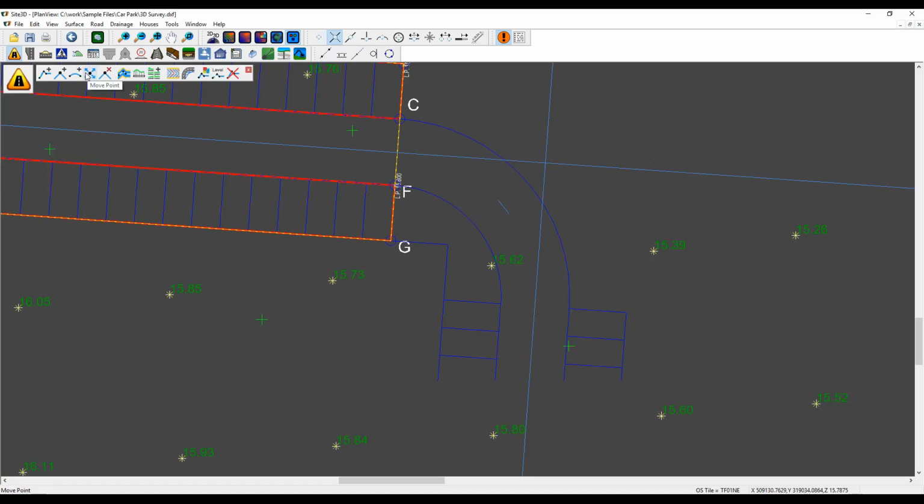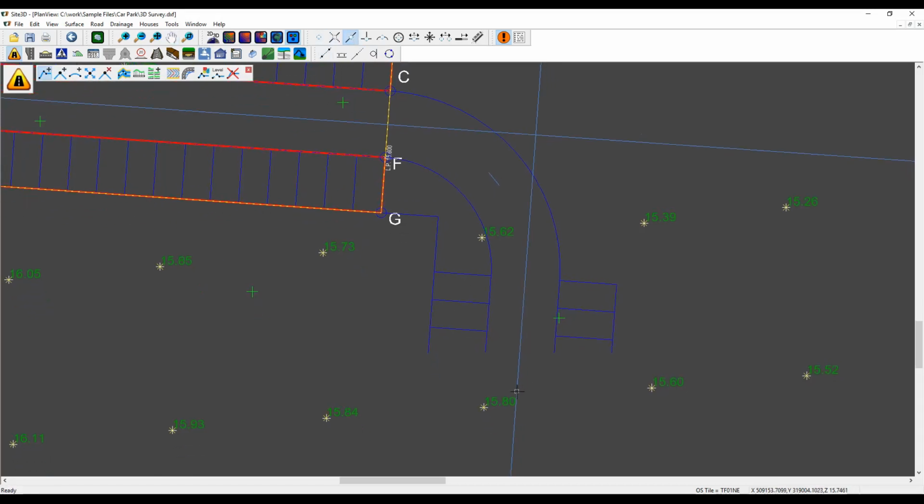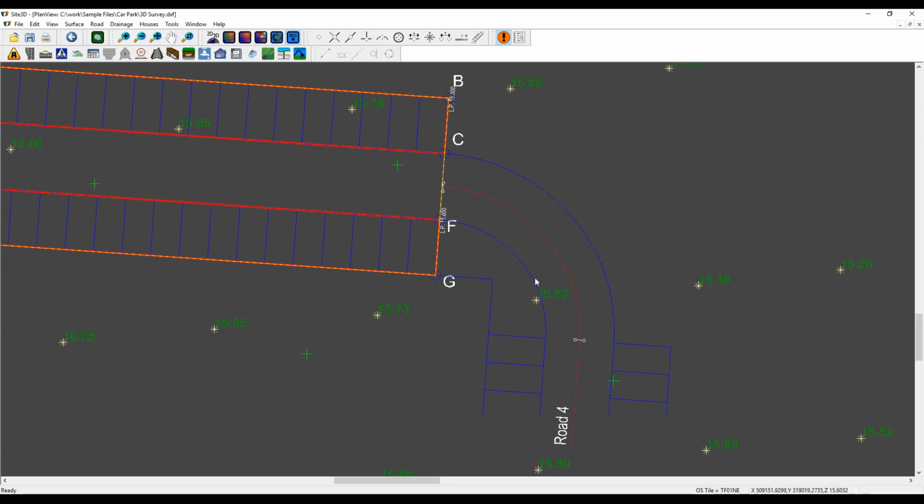So the next thing I want to do is put a new centerline in, and this time I'll start down here, so somewhere on that point. It doesn't really matter. Snap to intersection to that point, and then to there, and I'll set the radius using the snap to any point on the line to here. There we go. So we have our centerline coming in.